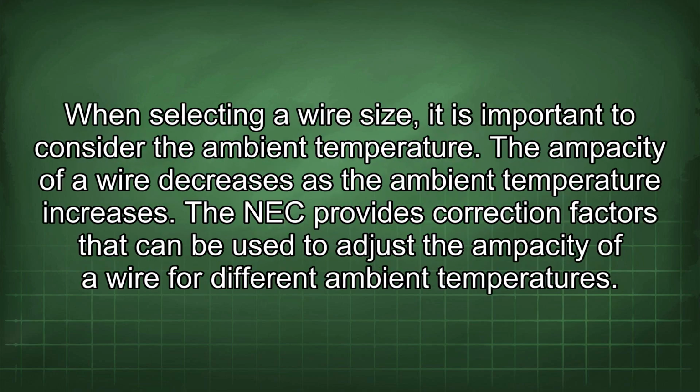When selecting a wire size, it is important to consider the ambient temperature. The ampacity of a wire decreases as the ambient temperature increases. The NEC provides correction factors that can be used to adjust the ampacity of a wire for different ambient temperatures.